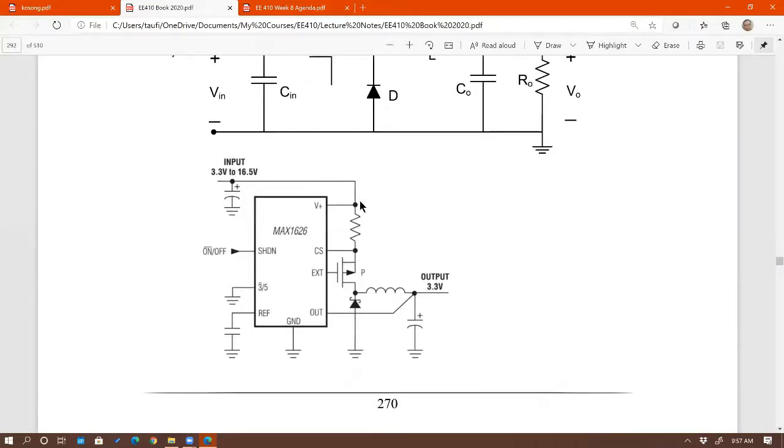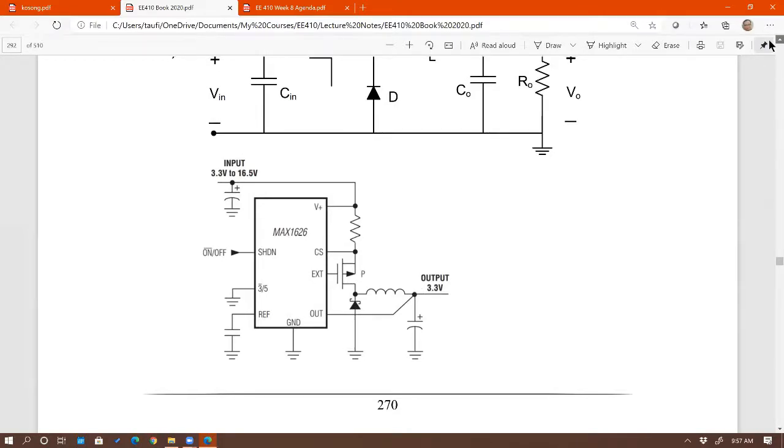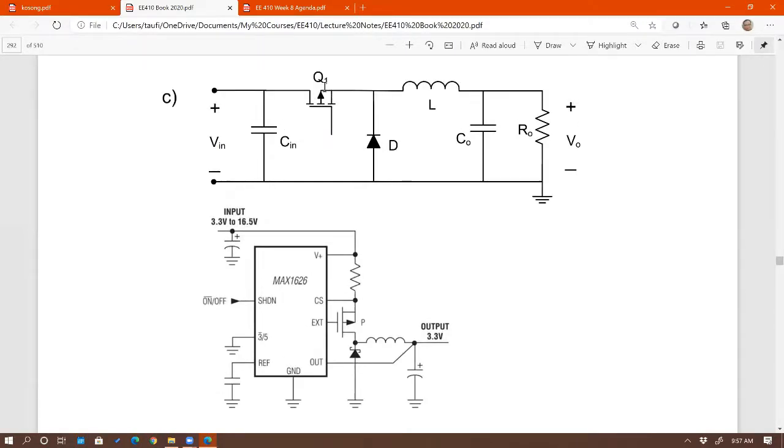All right, and then here is an example of a circuit that I copied from Maxim. To show you an example from a real-world data sheet, even from this data sheet you can see that there's an input capacitor right there. And this one is also showing a PFET MOSFET. I almost forgot about that. So here's a PFET right there too.